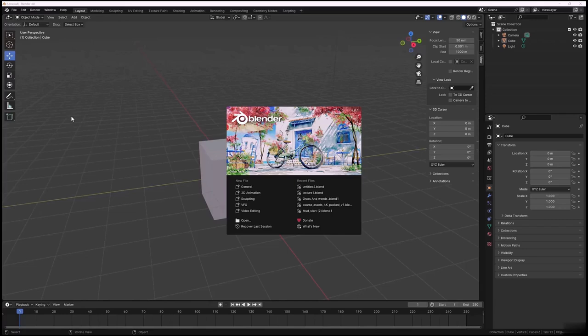We're going to talk about something called the Subdivision Surface Modifier, and this is a really important tool within Blender, and it's used generally in almost all mesh based modeling softwares. Whether it be 3ds Max or Maya or Blender, they all have a Subdivision Surface Modifier or a variation of that. What it actually does is increase the complexity of the mesh of the component. So we have to figure out how to use that without making the mesh of our item too much. I'll show you how we do it.